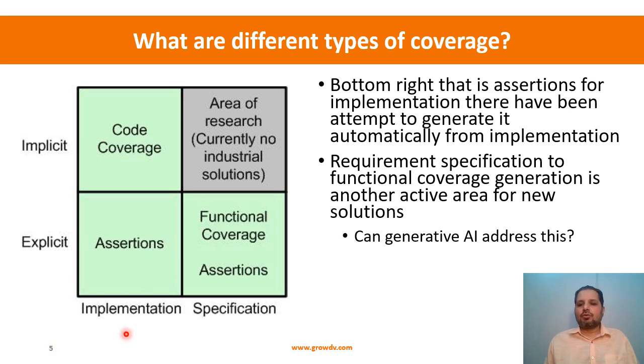So when I verify from both of those angles, I need to cover from both of the angles as well. I need to cover from the specification angle, wherein I will say it has to buffer so much and stuff like that. And then when it comes to implementation, I will say, yeah, 256 bytes, if it's a multiple of 256 bytes, 1 byte less than 256 bytes is a corner case for me, 1 byte more than 256 bytes is another important corner case for me. So I need to cover those implementation specific aspects, right?